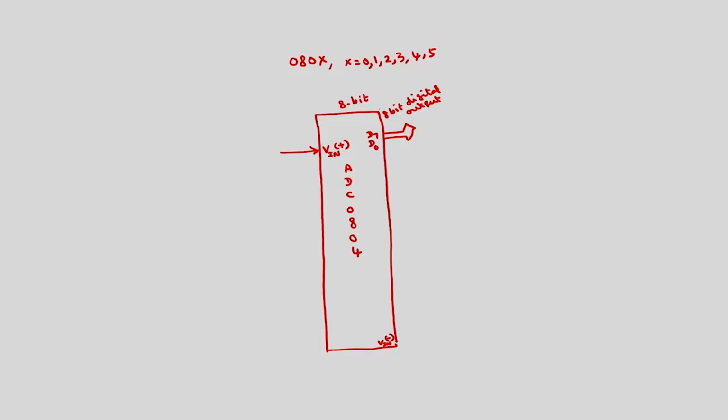Here this is V in plus and V in minus, these two inputs are the analog inputs. Why two signals are required is, the given input signal can be either positive or negative, or it can be a differential signal. We can apply sinusoidal types of signals also.